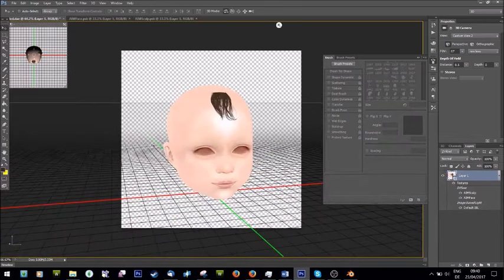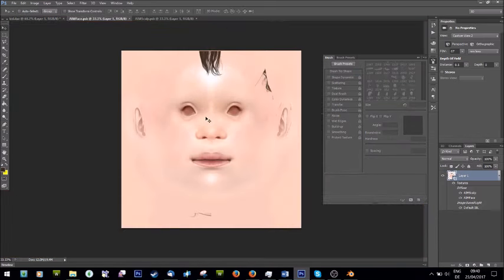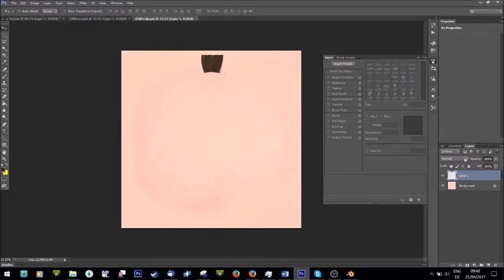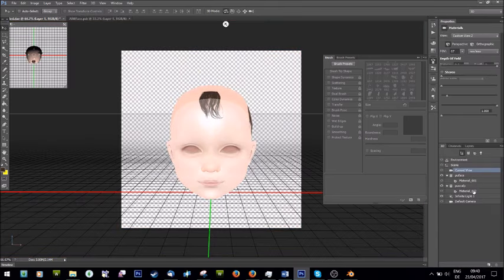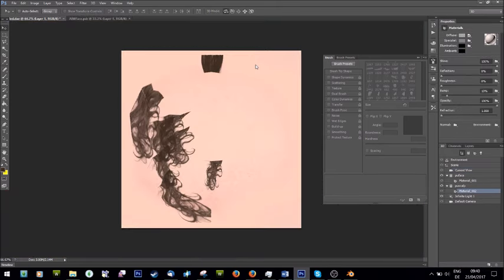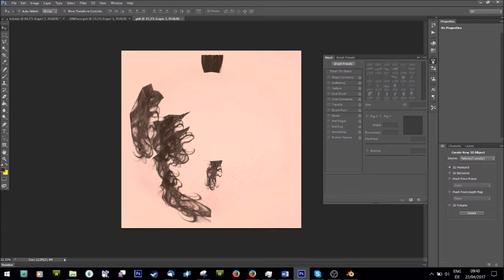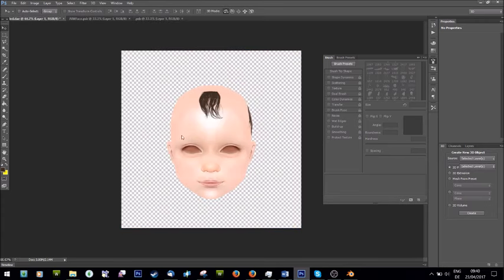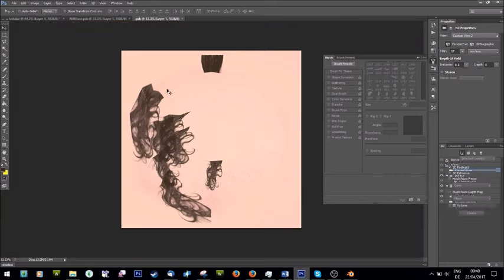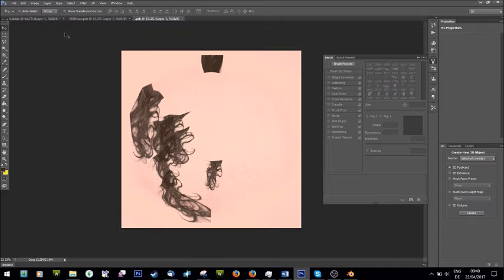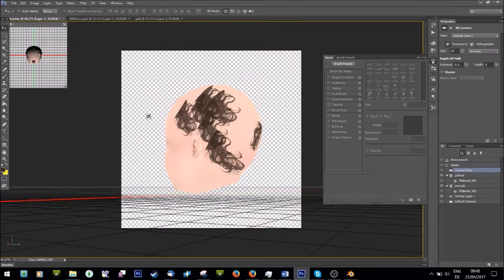Right. Now, if I go to these textures, you'll see it has my hair texture in exactly the places it needs to be. This one doesn't, because as I said, the syncing usually doesn't work for me. But if I go to edit texture again, you'll see it has it, and you'll see it's stretched on this texture, but is straight on the head. And this is because the 2D UV map is obviously a bit stretched. So if you don't want stretched hair, you just draw it on the 3D image.